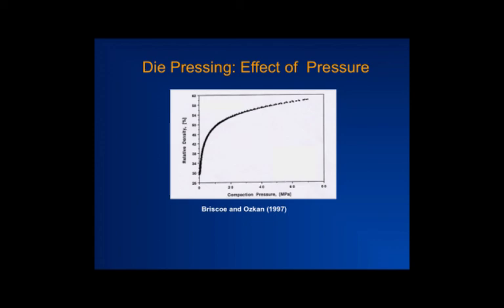So as the particles come closer together, there's more friction, and so the extra pressure that you might need to overcome that allows for a lot of dissipation of energy, right? So you're reaching the limits of mechanical deformation of the powder, based on the material characteristics. So for iron powders or some aluminum powders, you will be able to go through a much steeper curve compared to a ceramic material, where it will flatten out much faster because the material is a lot harder.